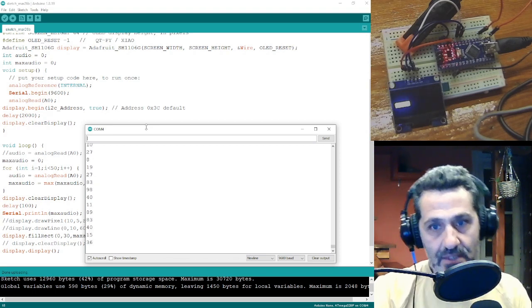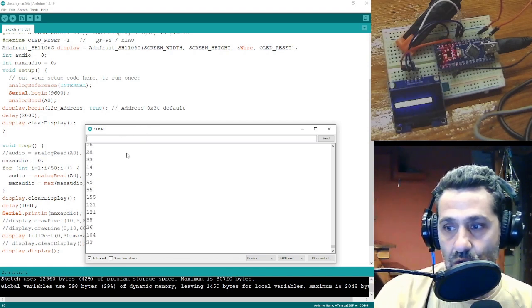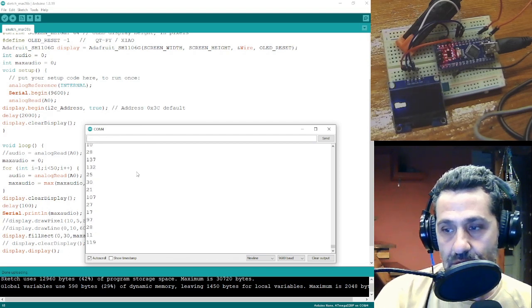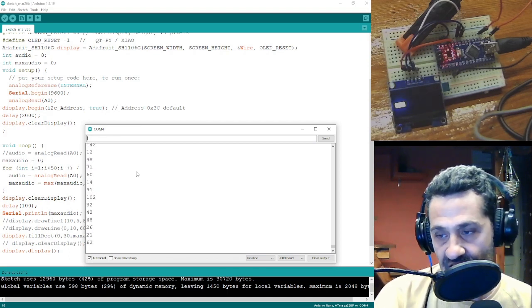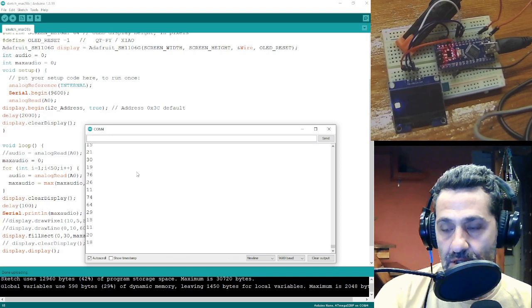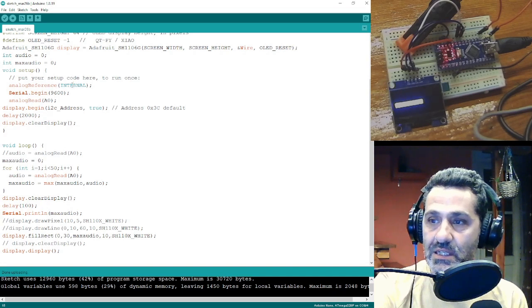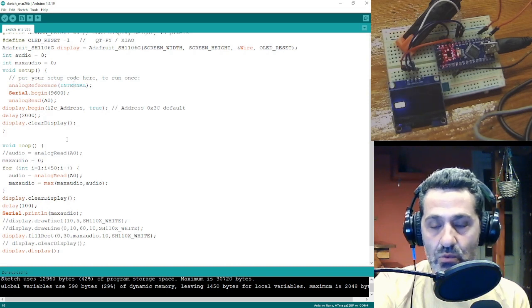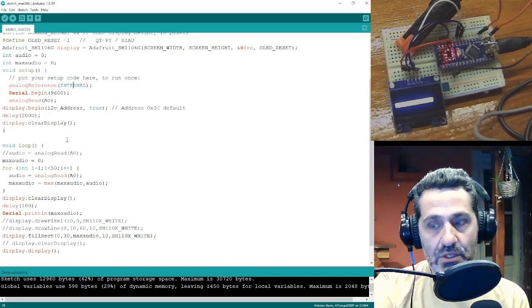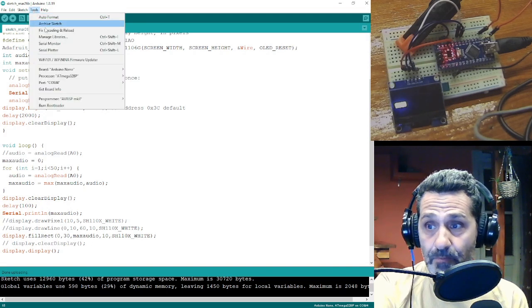so as I can understand, the values that I am receiving are generally in the range of up to 0.5 volts or something like that, because with this internal command, the maximum voltage that we read is 1.1 volts, and the Arduino would output the value of 1023.